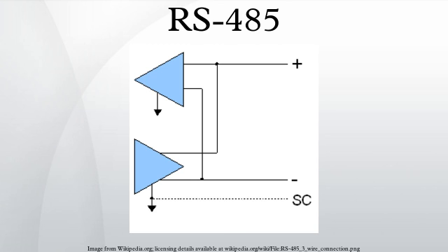Applications: RS-485 signals are used in a wide range of computer and automation systems. In a computer system, SCSI-2 and SCSI-3 may use this specification to implement the physical layer for data transmission between a controller and a disk drive. RS-485 is used for low-speed data communications in commercial aircraft cabin vehicle buses. It requires minimal wiring and can share the wiring among several seats, reducing weight.